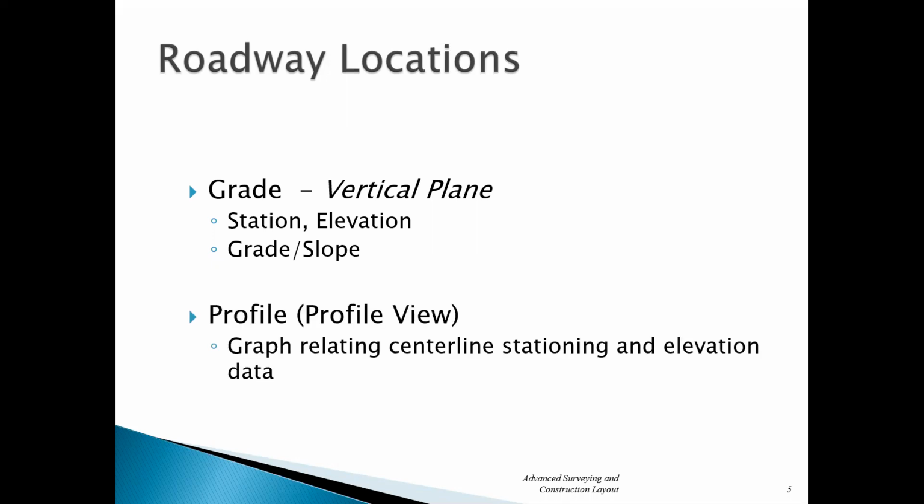And this is occurring in the profile. Well, actually, I guess I should take that back. In the profile, this is what's following the center line. I kind of got ahead of myself when I was talking about slope stakes. Those are typically in the cross-sectional view. So the profile is basically a graph that relates centerline stationing and elevation data.